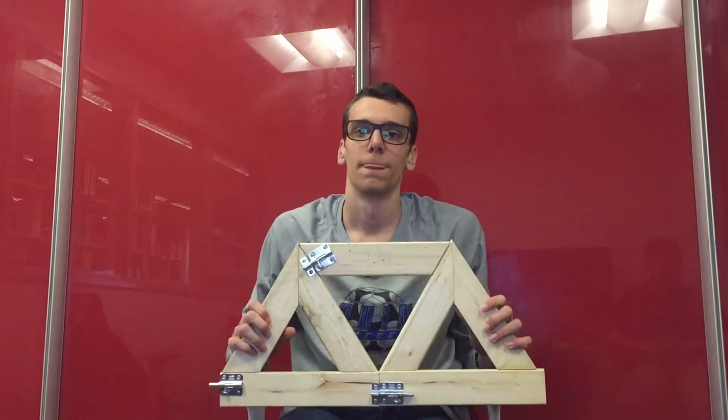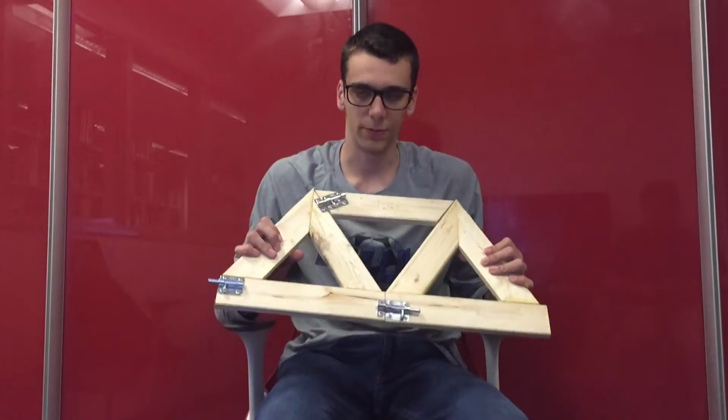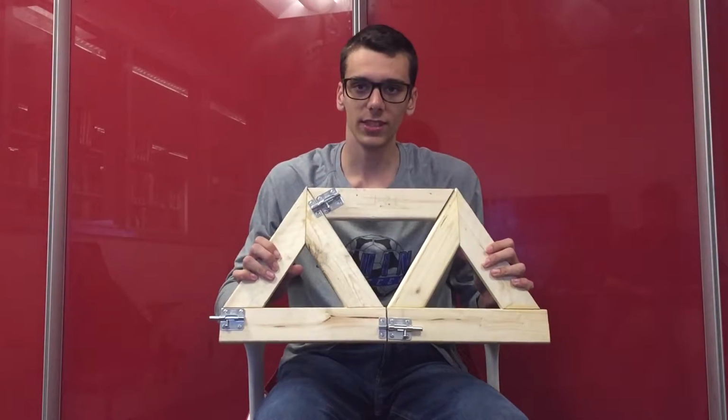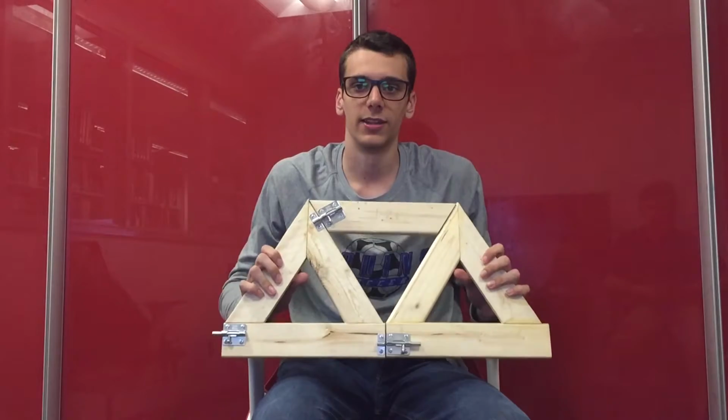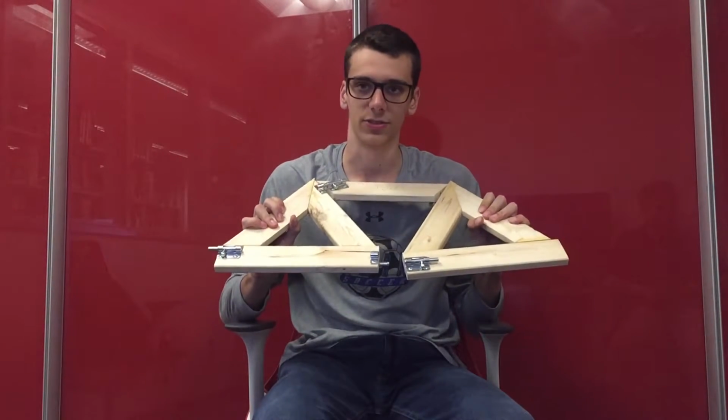The last portion of the engineering design cycle is to improve. While following our plan, we ran into several design challenges which we innovated new ways around. The first challenge we had was with the bolts that connected the 4 triangles together. There was too much of a gap between the bolt and the part that held the bolt. This allowed the triangles to wiggle, making the bridge unsecure. When force was applied, the bolts would loosen and fall out of the holding position.